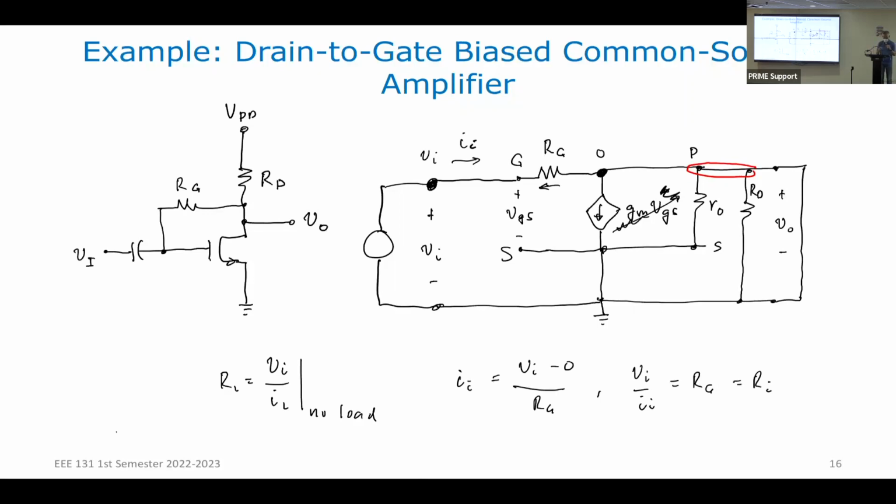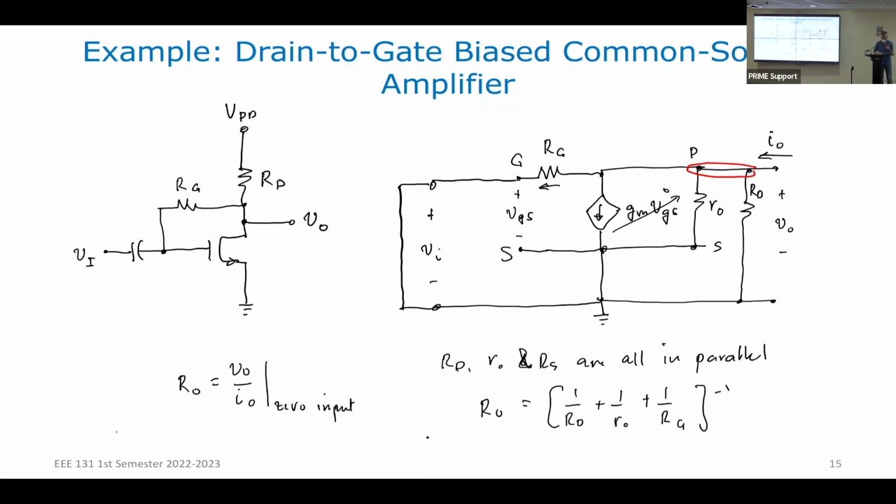Okay, I want to mention something which is important to take note of. Balik tayo dito sa Rs of O. Note that if my input had been a current source, I would have had a different result. Because ano yung zero input pag current source? Ibig sabihin open circuit yan. If this is an open circuit, this is no longer equal to 0. There will be some value here.